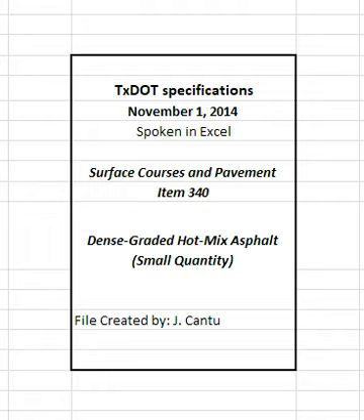The engineer may allow compaction with a light finish roller operated in static mode for pavement temperatures below 160 degrees Fahrenheit. Allow the compacted pavement to cool to 160 degrees Fahrenheit or lower before opening to traffic unless otherwise directed. Sprinkle the finished mat with water or lime water, when directed, to expedite opening the roadway to traffic. 4.8 Production acceptance.